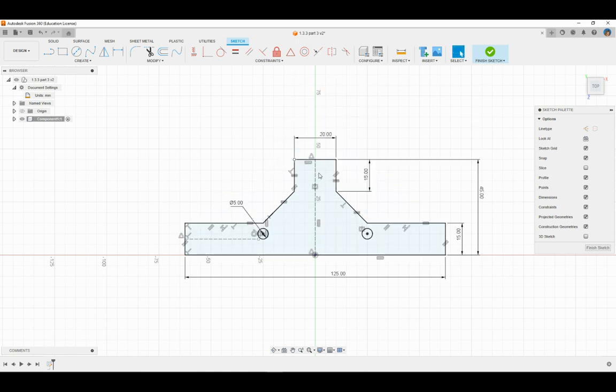So what if I wanted my shape to be 100 millimeters, but I only wanted this part up here to get longer? I wanted 5 and 7 to get longer. I want 4 and 8 to stay the way they are, and I want 2 and 10 to stay the way they are. What would I need to do? In order to make that happen, we need to go over here to our 15 millimeters for line 7. We need to left click, right click, and hit delete.